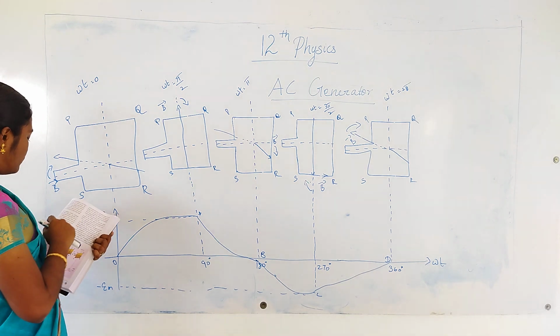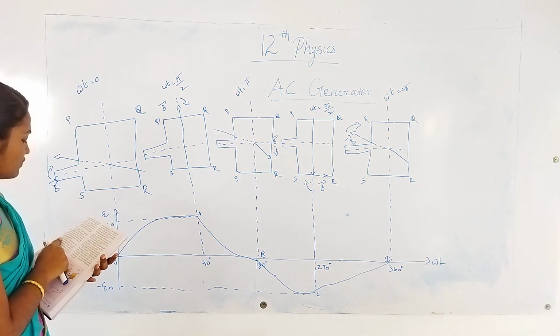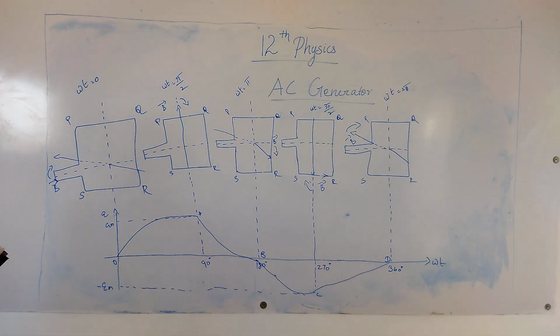right hand rule. The thumb indicates the direction of motion of the conductor with respect to the field. For a clockwise rotating pole, the conductor appears to be rotating anti-clockwise. Hence, the thumb should be pointed to the left. The direction of the induced EMF is at right angles to the plane of the paper.